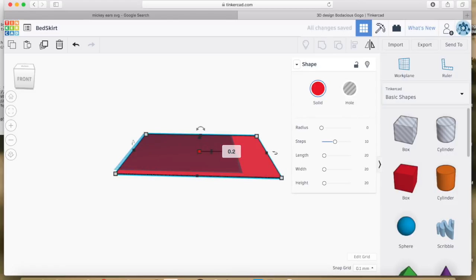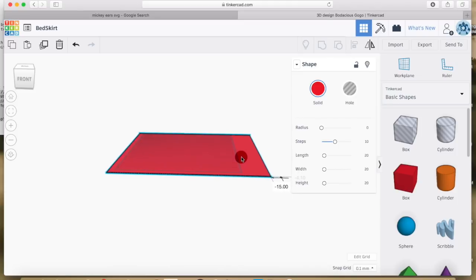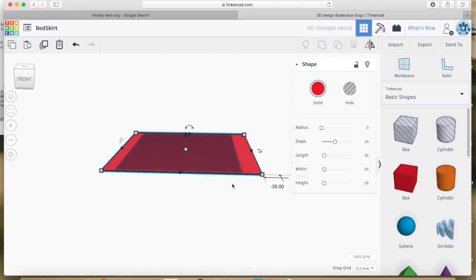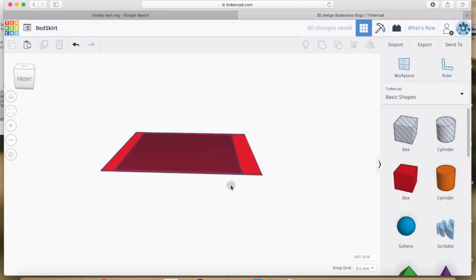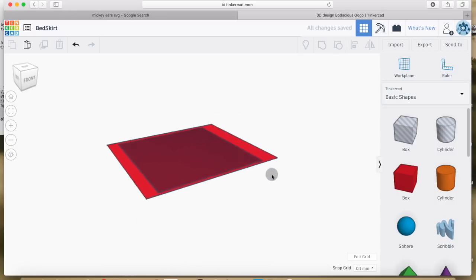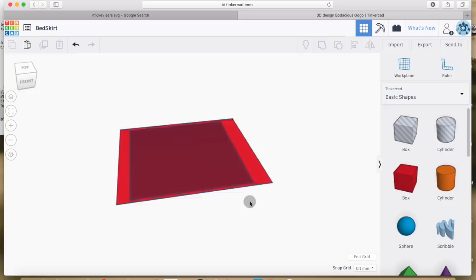And then after you save it as STL, you could change it to another layer height and save it again. But you do want to set it to your layer height. I think if you use the wrong layer height and go ahead and print, or maybe use a thinner layer height, you're not going to run into any problems, but it's just easier to make a couple. Alright, so now we have this sheet here that represents our bed, this nice rectangle.